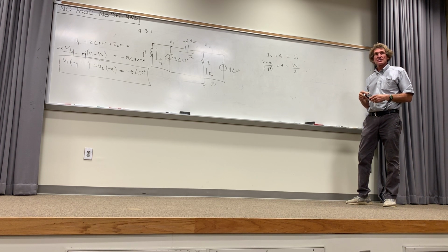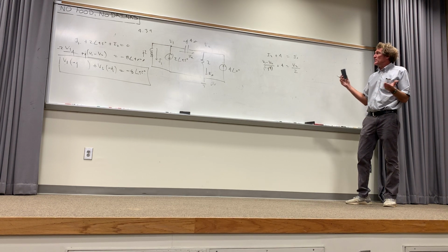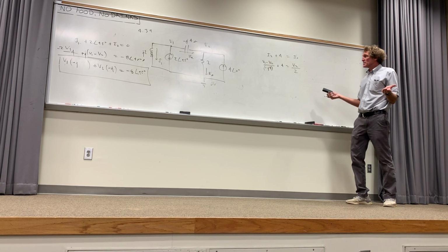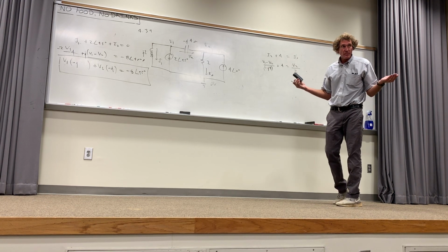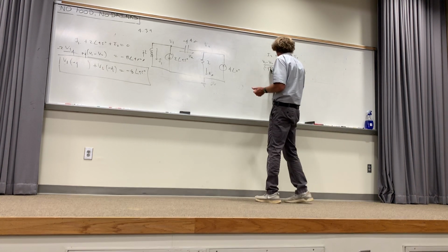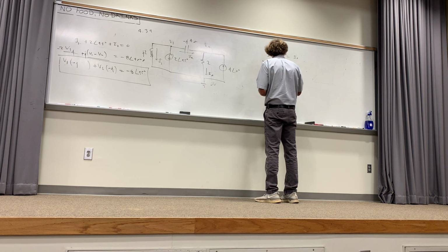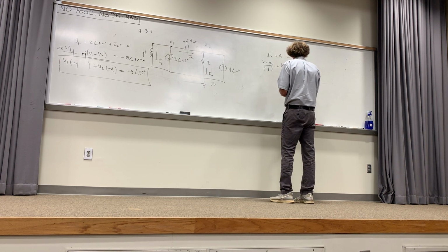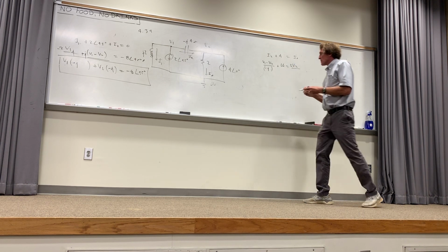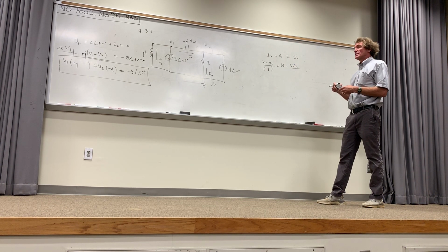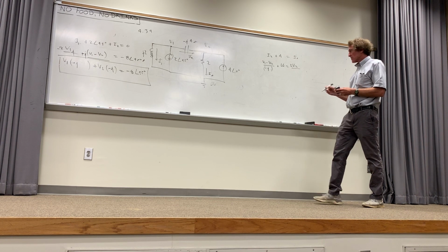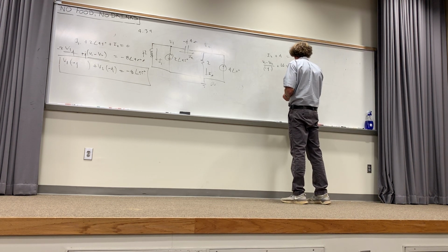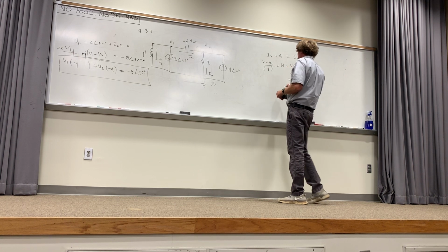Again, just the voltage differences across the actual components divided by the impedance of the components to get the current, right? Everybody? Now, how you solve it's up to you. You can almost guess what I'm going to do first: multiply by 4. I don't like fractions. I multiply by 4, and I get 16 here, and then I get 2 here. Right? After that, I'm going to take the 16 to the other side, so now I'm going to have minus 16. Right? Then I take 2v2 to this side.